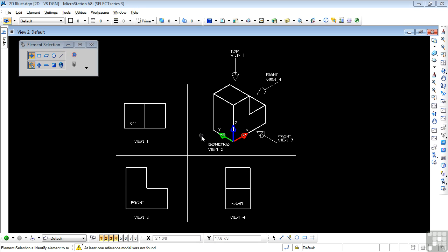Now, as you know, MicroStation provides 8 standard views for viewing the design, and you could in fact have 8 views open at once. Unlikely, but possible. Mostly you'll be working in the isometric view, with the occasional look at the remaining 3 orthographic views. And right now it's very important that you understand where these views are coming from and how MicroStation is seeing elements.